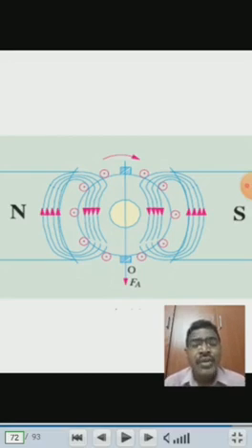If you want to find the direction of current flowing through the armature, you can apply Fleming's right hand rule. Then these two armature fluxes produce MMF, which is in the direction of the magnetic neutral axis, the vector OFA. That represents the magnitude and direction of the armature MMF produced by this armature flux.